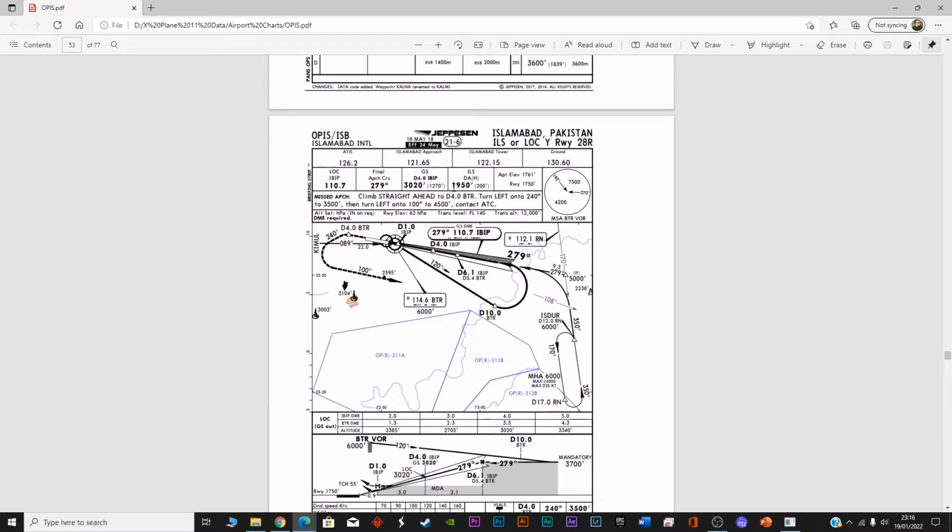And then this is the decision height, which is 1,950. The elevation for Islamabad International Airport is 1750, 90 as I told you before. So this information we know. And the decision height is 1,950, almost 200 feet above the ground. This is the decision height at which you can just decide to declare a missed approach, or go around, or if you want to turn back.